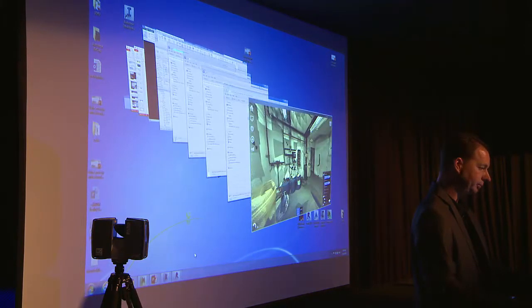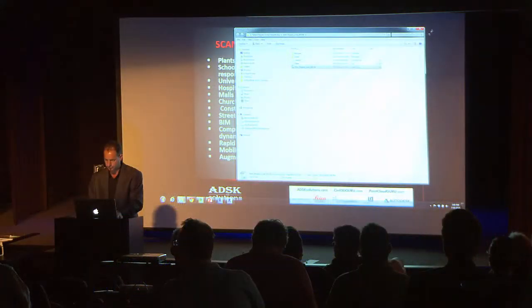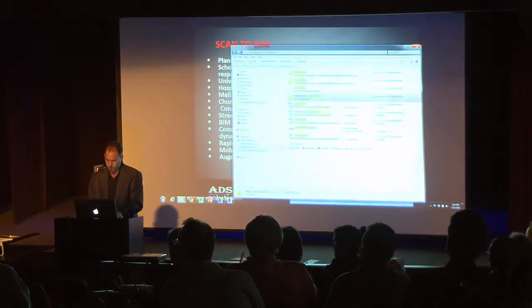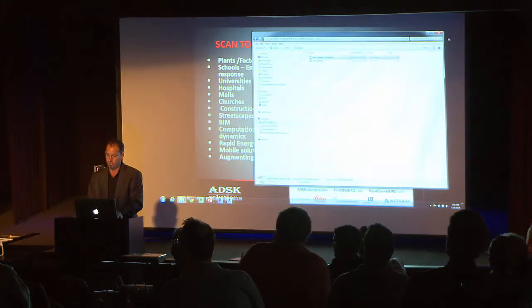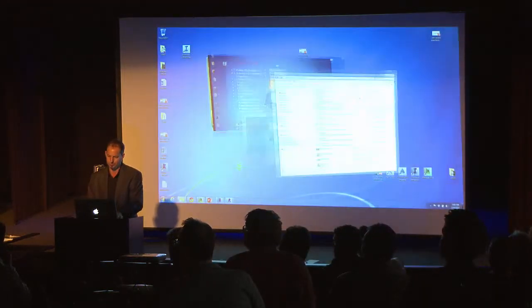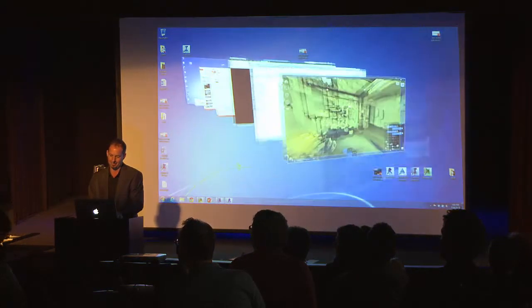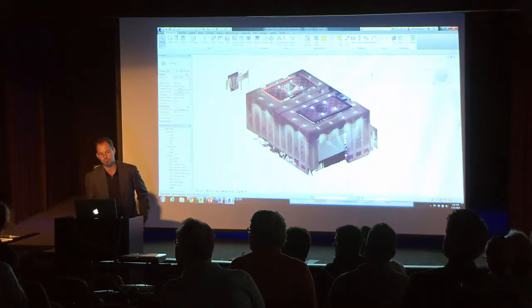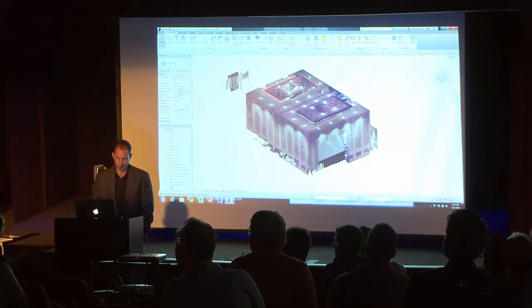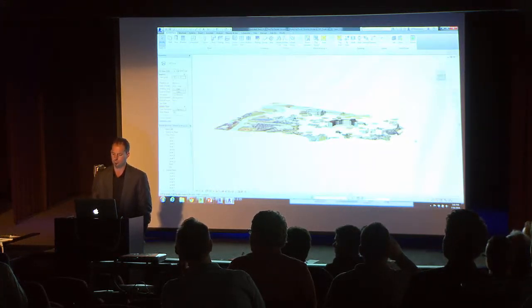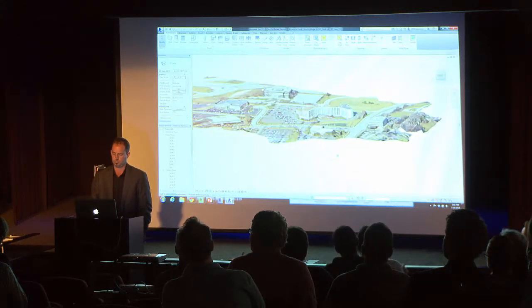Yeah, absolutely. We've talked a lot about using GoPro to do the photo reconstruction. It does work very well if you have the GoPro Hero 3 Black Edition, which is the one with the highest resolution. The other can't. 400. Yeah, 400 exactly. We actually have to model the camera lens for each of these different cameras, which are very different. So we've got the one for the Hero 3 Black. That's what we use to do all our examples. So the Silver are not supported. If you try that, you may not get the results that you want.